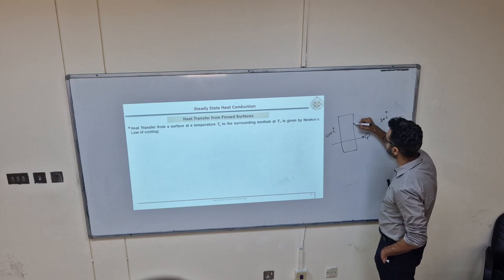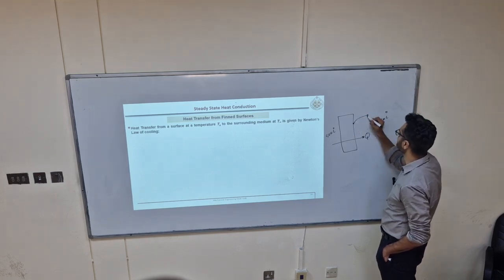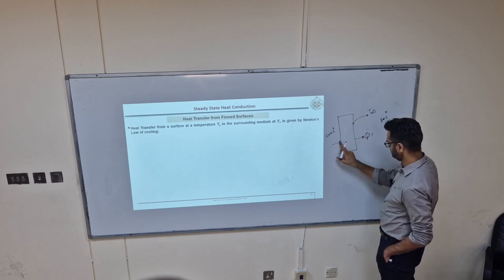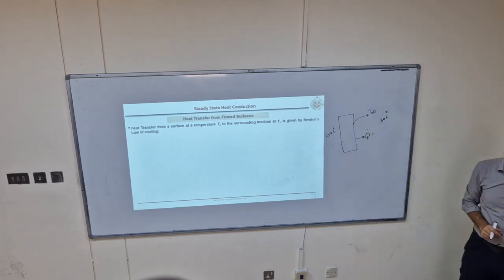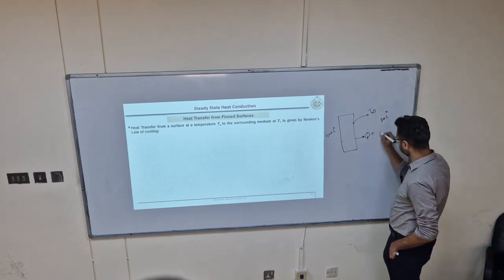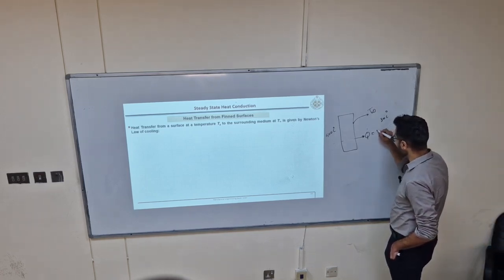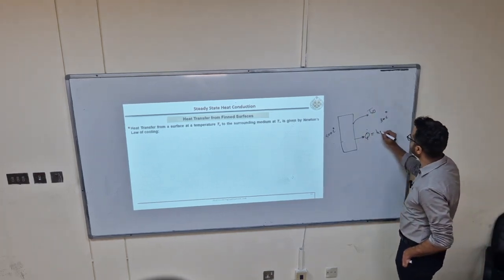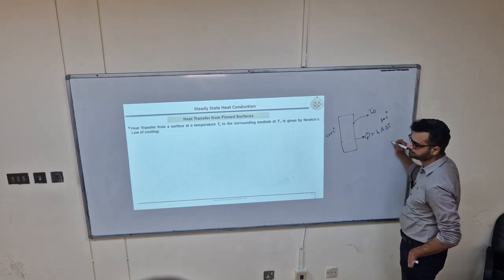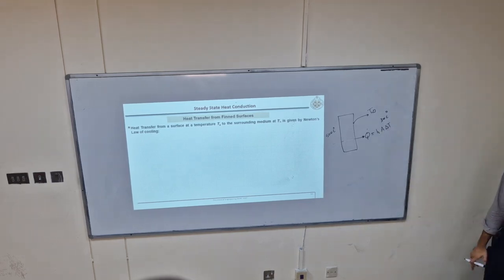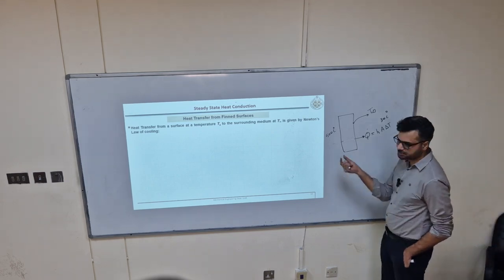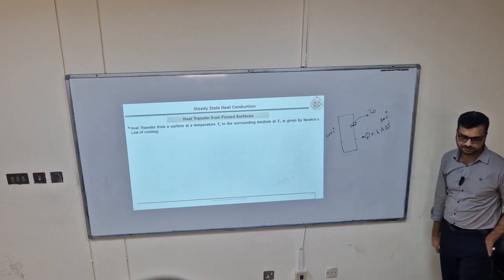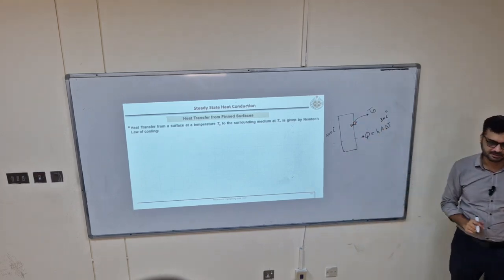Okay. So now let's take this part from this edge to ambient. So this Q dot is given by, from this edge to this fluid, what is the equation? It's all convection, neglect radiation. So it's by convection, H A delta T. It's a metal wall, a very thin metal wall, so this will also be 500. Right. Neglect this conductive resistance.